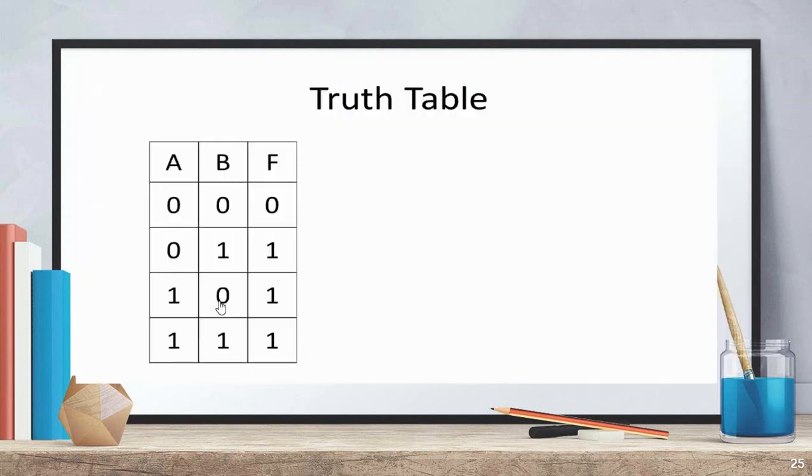Let's look at an example. Here is a simple truth table with 2 inputs, or shall we say 2 variables. You should recognize this as the truth table of an OR gate. Column F contains the output value for each combination of input values A and B. Strictly speaking, this is the truth table for any combination of logic gates that behave in the same way as an OR gate.